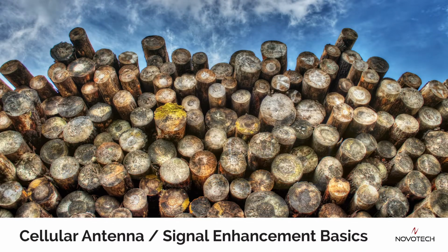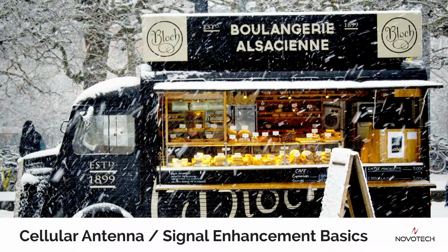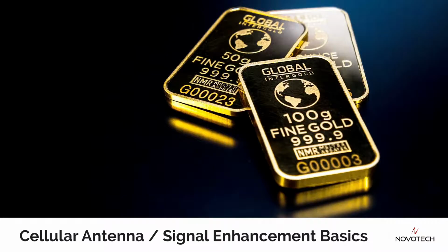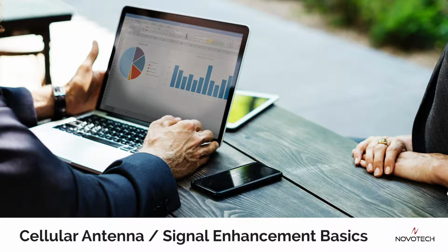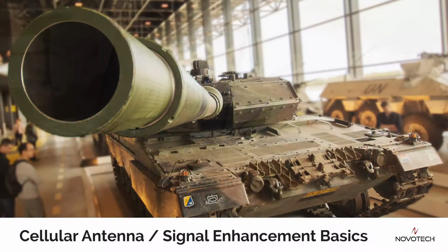1. You are deploying in a known bad coverage area. 2. The site is mobile and the coverage levels are not known. Or 3. It is a high value site where bad signal strength is simply not an option. These antennas provide an enhanced signal reception and tend to use a cable designed to minimize any signal loss. They definitely are more expensive, but the extra durability and performance is very easy to justify.